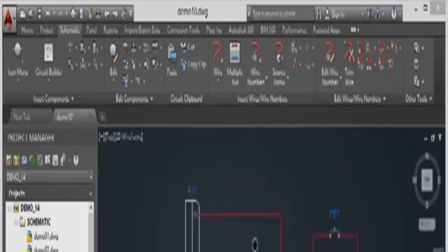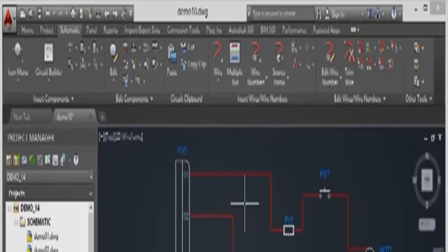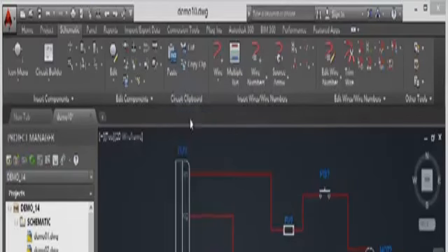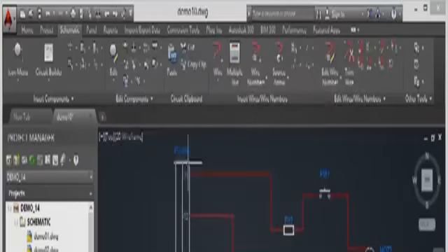And if I zoom in now, you'll see it's the same as the W blocked circuit that we brought in previously. I still need to go in and tag it. It's brought in the tags, but it doesn't know what the numbers are. So I would actually need to use Edit Component now. Notice everything is still a component. It's all been brought in. It's not separate blocks or anything like that. I can edit that component. I can change that to, let's say, 300. Click on OK, and that updates in the AutoCAD Electrical drawing.